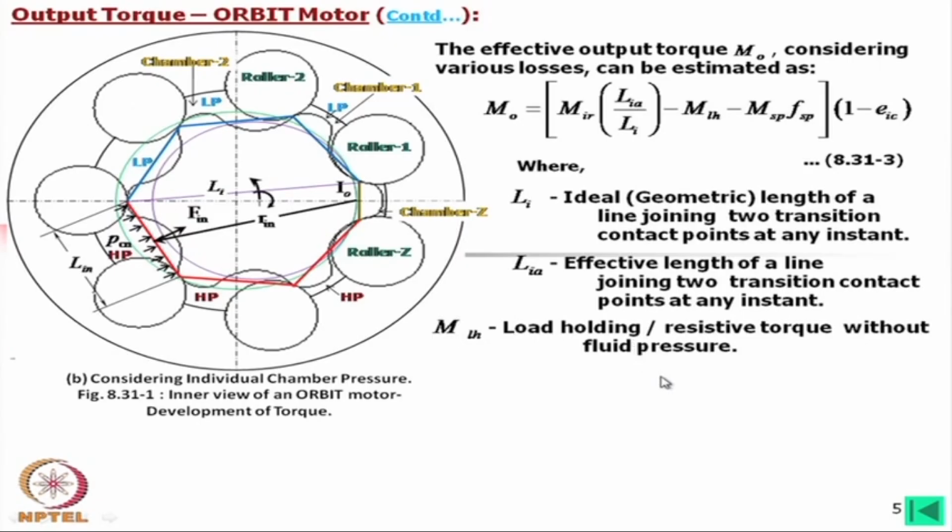That means we need a torque to start this motor without any load, that is the load holding torque. On the other hand, this load holding torque we can also name the starting torque required. Now, obviously this increases depending on the fittings. If the fitting is too tight, this part will increase, and that can be estimated. Also, this is normally found out from experiment.